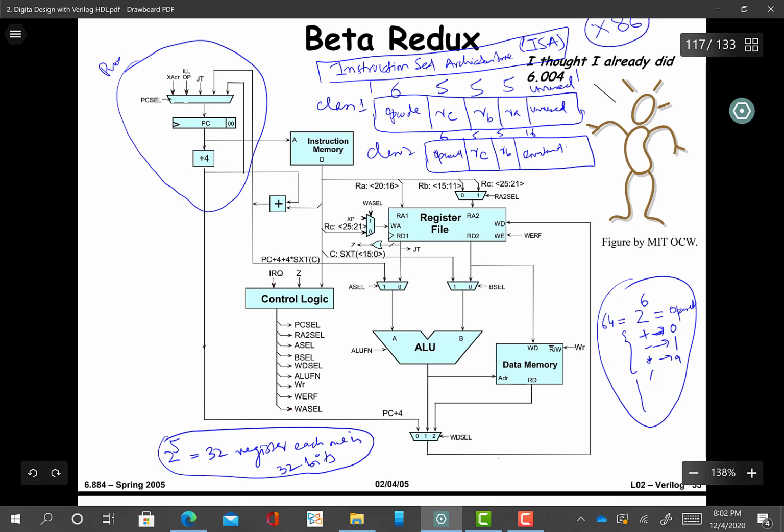The program counter is basically a counter that points to the instruction memory. So here is your program. Maybe you have written the program in C or C++, and then you generate the hex, and the hex goes to the instruction memory. On each cycle, your computer reads a 32-bit instruction from this memory, and the next instruction is 4 bytes away.